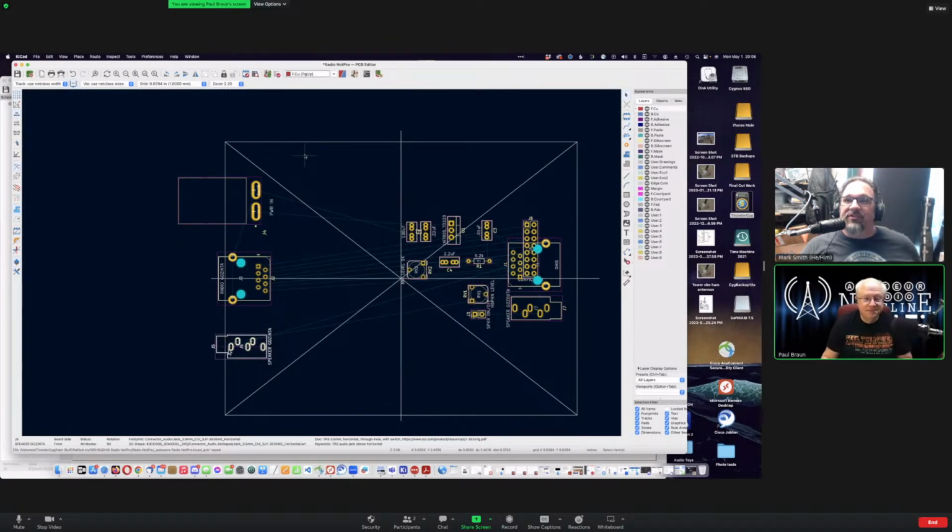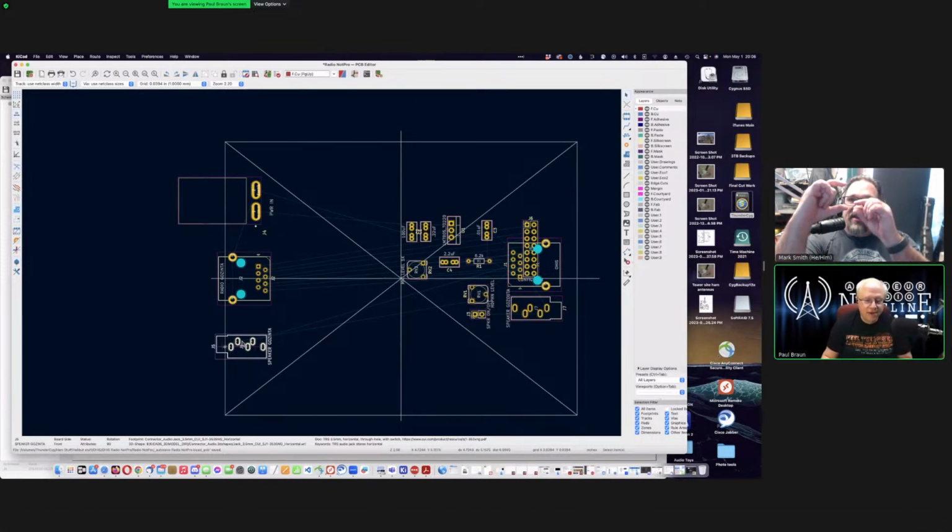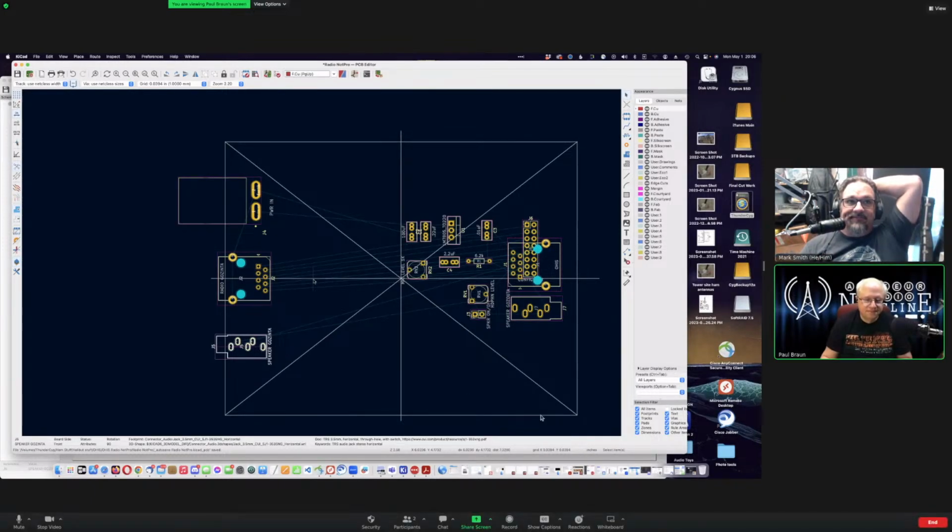I would also put the anchor right at the front of the larger width, in the center of the round part. Like right here. Right there, exactly. That way you can grab it by that anchor and snap it to the board edge, and then draw a dimension between that anchor and the board center line, and you know exactly where to place that circle. Yep.